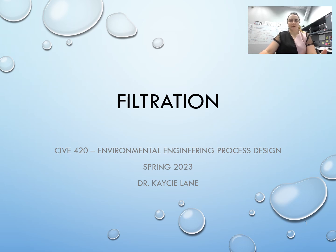All right, so let's talk about filtration. So we've coagulated, we've flocculated, we've settled things out of the system, and filtration is really the backbone of where we start to remove pathogenic organisms and we start to really polish the water so that we're ready to go when it comes to disinfection.